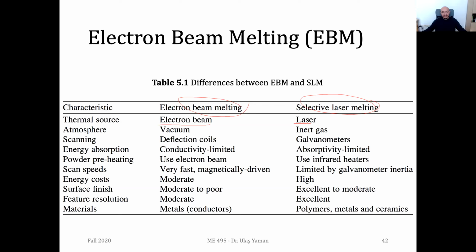Yep. It's like powder metallurgy. If you do not have any further processes, then you can easily break your part into smaller parts. They are in a green state. You can call them a green compact, sometimes a brown part. They do not have enough strength, so you cannot use them until they are sintered. You need to do further sintering operations.